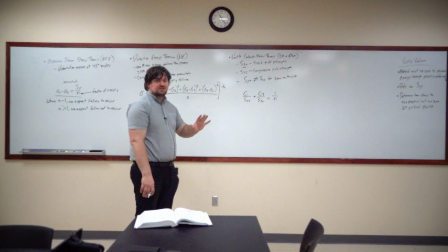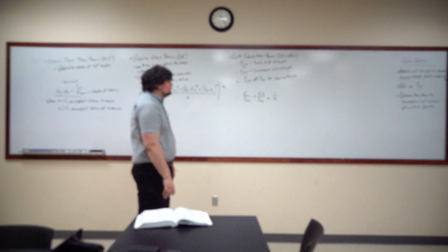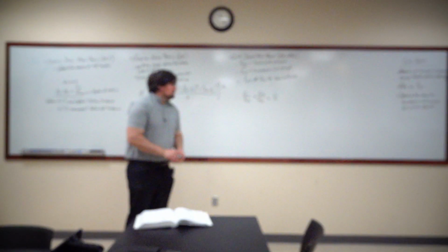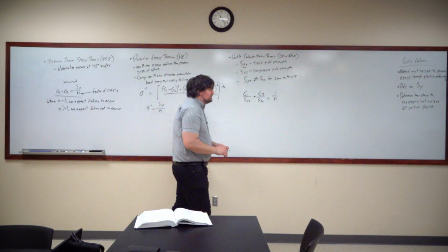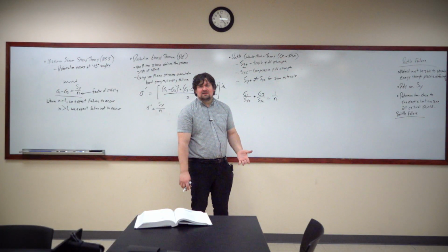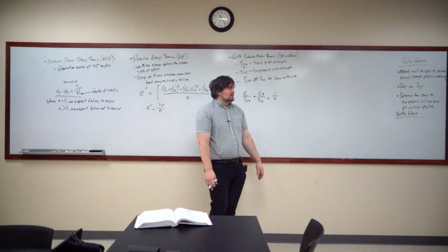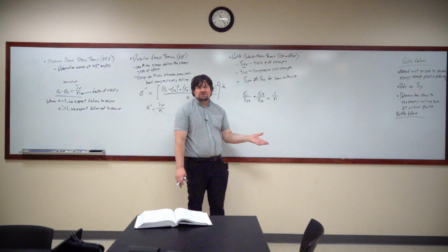Now that's our 3 ductile failure theories. We also have brittle failure. Now when I say brittle failure, it is actually possible for any material to experience brittle failure. If you've ever dropped a piece of plastic, or like a plastic container, and the plastic container just shatters, it's experienced brittle failure.